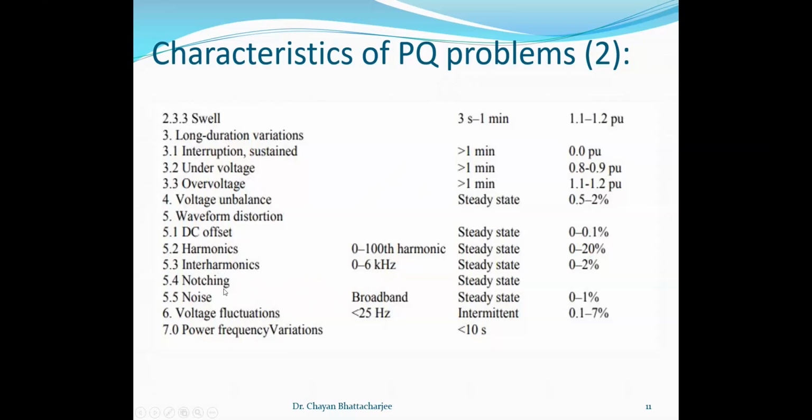Notching is another problem. It is also a steady state disturbance. It is a continuous disturbance of the voltage waveform that is caused by power electronic devices, generally voltage source converters. It is generally caused by the opening and closing of the switches of the converter legs.